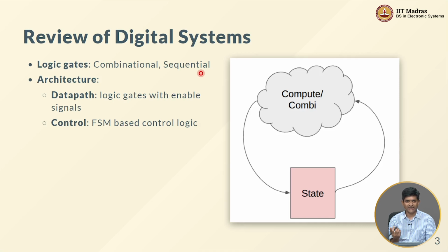So, for the most part that is the one that we are going to be focusing on over here, right. Edge triggered D type flip flops primarily because we have a very clear kind of functionality when there is an edge, a transition from 0 to 1 which is called a positive edge or from 1 to 0 which would be called a negative edge, depending on what kind the flip flop is sensitive to. When there is that transition, the output of the flip flop will basically take whatever was there on the input and copy it over to the output, right.